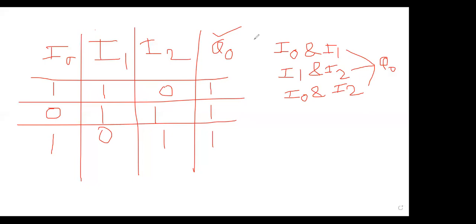So I shall go for the next example. Look at the screen, everyone. This time we are having two inputs, I0 and I1, and three outputs. See, till now you have made it for one output, correct? For one output, you took a coil and made all true conditions.